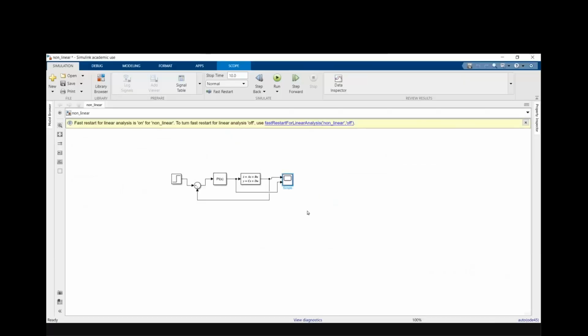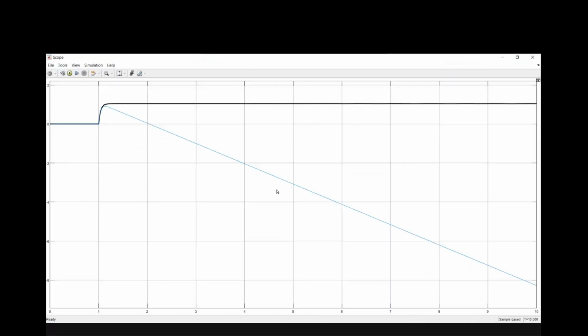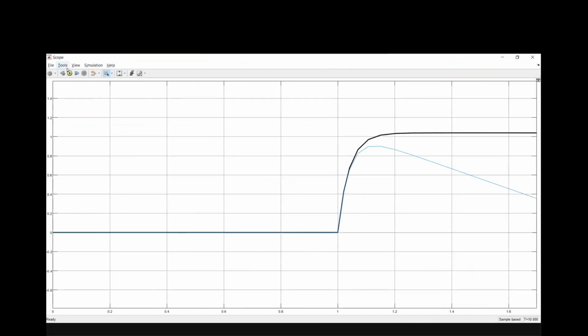Okay. What is my second one? Second one is my PI controller and first one is my output. See, the PI controller is becoming nonlinear to make your system bounded. Let us see this. You got it right. Though your system is unstable, this is actually, I didn't do that, but it happened. Though my system is unstable, you can apply PI controller if you have a linearized system.